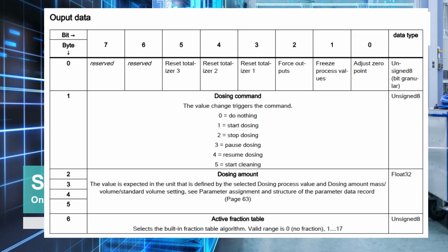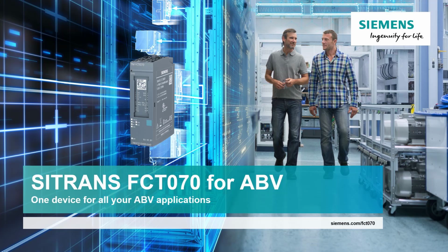It's important to realise that when you look at your standard way of producing distilled spirit, we use hydrometers, and when you look in the whiskey safe in this case, you'll see two: one for the high range and one for the low range. So even with the conventional method of measuring density, we can't achieve the accuracy with one measurement device.